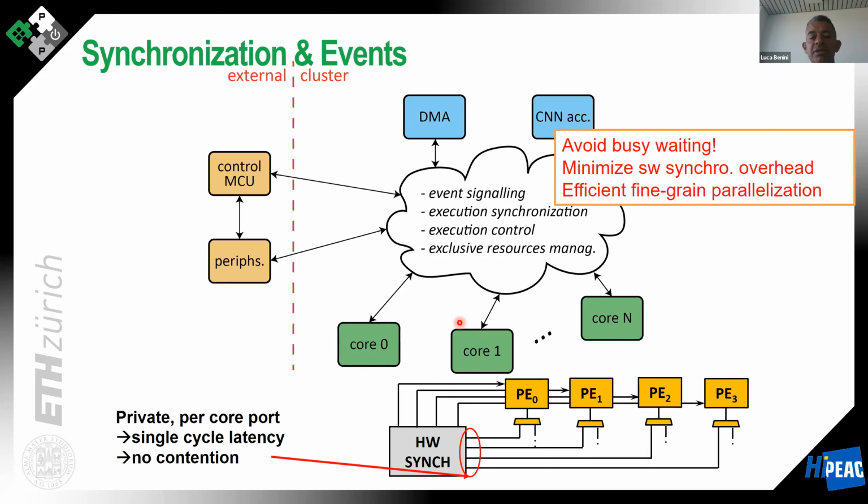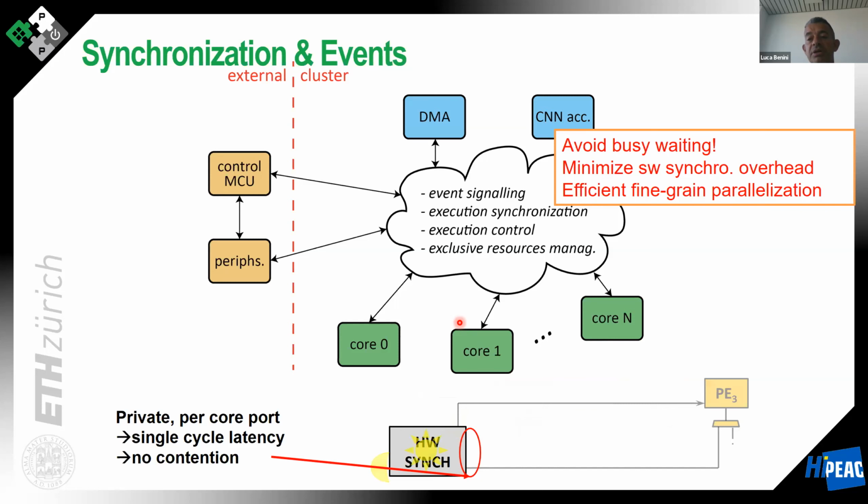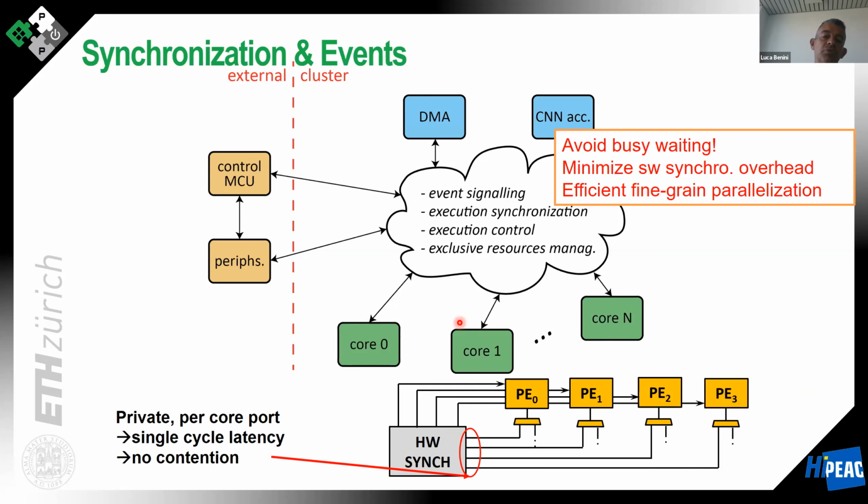So we implement this using a specialized synchronization unit, which is fast and extremely energy efficient. What is the concept here? The concept is that whenever a core has finished, it will send a signal to the synchronization unit and it will put itself to sleep. Then the synchronization unit will count all the signals as shown here in the animation.